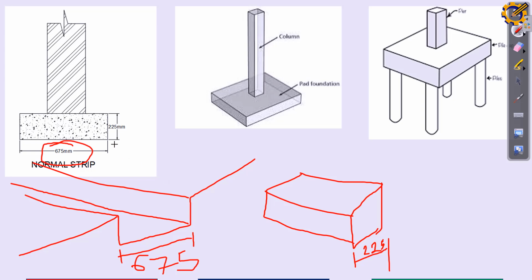And the concrete binding that will be sitting there, the thickness is going to be 225, the thickness of my block. Actually you can do more than this, but this is just the minimum. After doing that, your wall will now sit in the middle, like this.